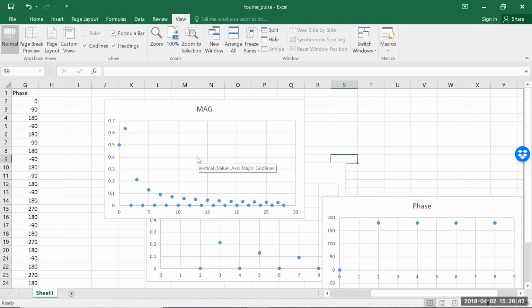Now, if I was trying to create a sine wave, maybe I would just want this, right? And I would use a band pass and get rid of the DC and then try to get rid of all of these. And if I wanted, I'm not quite sure what I would call it, a high pass where I would sum these and get rid of that. But really, we're trying to get this signal at n equals 0, or a frequency of DC. So this is the bit we want. That's the bit we don't want.